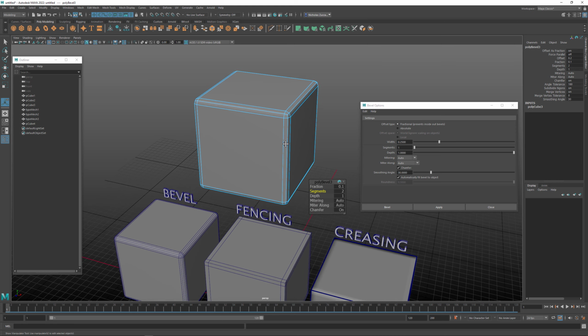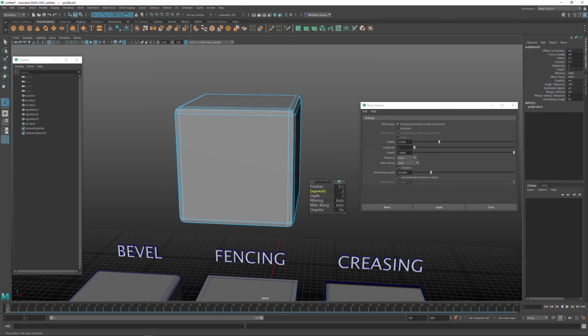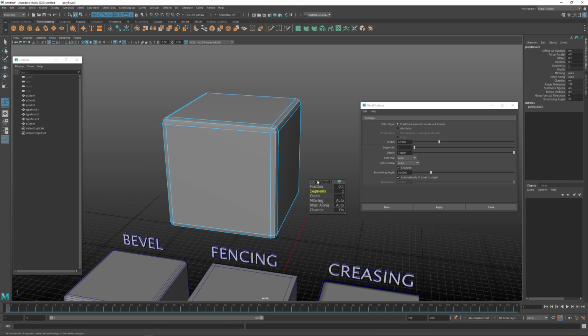Now what I want you to see is there's certain numbers for the segments that will allow us to continue to take this face that's generated here, and I want it split in half. That way we can always keep a top, front, back, left, right, top. So if we do a segments of 2, you can see that gives us a split right down the middle. Now if we do 3, it's not going to, but if we go up to 4, it's going to add enough geometry where we still have these splits that we can split this off like this for these different faces on there.